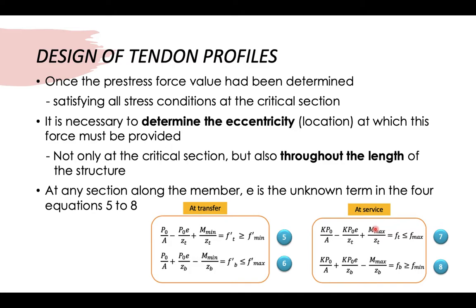Okay, so for the design of tendon profiles, once the pre-stress force value has been determined, which satisfies all the stress conditions at the critical section, it is necessary to determine the eccentricity, which is the location at which this force must be provided.